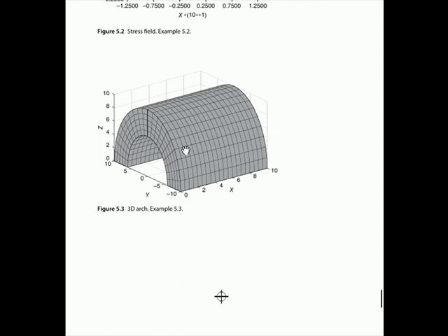So with a 3D problem with PDE 2D, you're going to basically have 6 boundaries. P1 equals its 2 extremes, and P2 equals its 2 extremes, and so forth. So we've got at most 6 boundaries. 3 of them are going to have 0 displacements, u and v and w equals 0. So it's basically glued to the ground and nothing can move here and here. It's also glued to some wall. There's a wall back here and it's glued to it. But on the top and the bottom and the far side, we're going to have 0 forces.